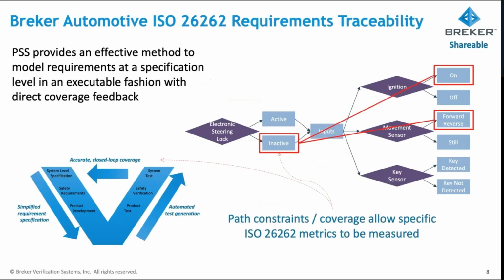So looking at this V model, what we could do is create a model of aspects of these requirements. And once we create this model, use synthesis technology to actually drive the test vectors for a range of different potential engines, simulation, emulation, even formal, and pick out using constraints specific areas that match the requirements that we want to test, and then use those to generate the coverage reports that allow us to prove that we've actually tested these things.